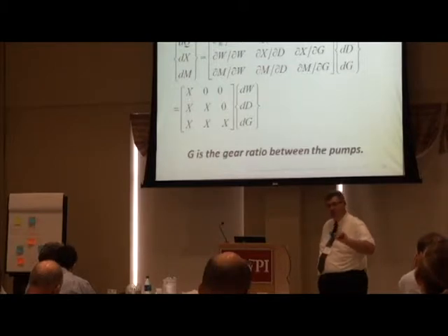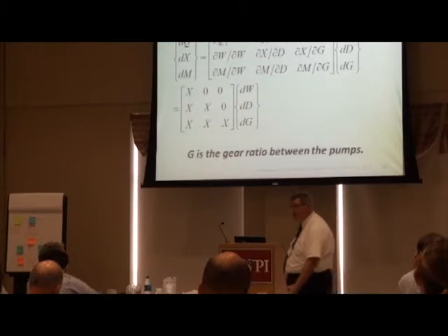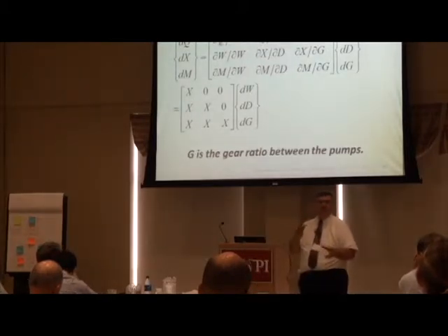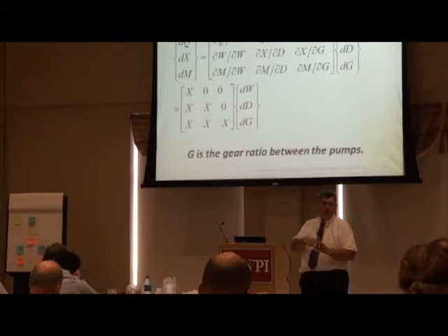But if you go too slow, then things get too hot and you end up with the edges not looking so good because you have too much energy in one spot. So you're always optimizing how fast you're going versus how much oxygen is injected into the cut, and you're looking for this optimal situation.